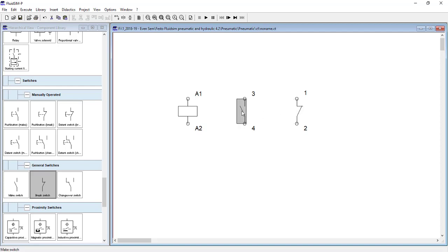Now this is a general symbol of normally open and normally closed. This will also be used for other things such as proximity switches and all, but it is also the symbol for relays normally open, and this is the symbol for relays normally closed. Now see, initially what was my requirement? My requirement was that I have to create a circuit in which when I push one push button, one motor should turn on and the other should turn off.